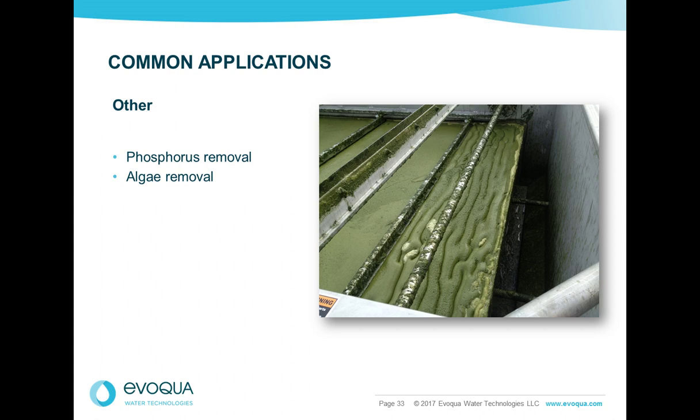Even DAF systems going downstream of membranes where phosphorus removal can only be accomplished through tertiary treatment using a DAF. And in small municipalities and large industries where there may be large lagoons and algae is a problem, algae removal is required using a DAF technology.